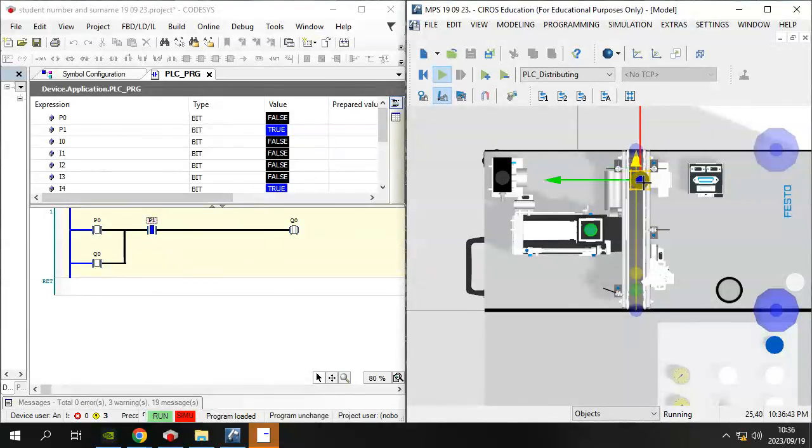Then let's go on top of them. So you see your, I think it's I2, or what is it? I2 turns on and off. So when it's not having a workpiece next to it, it's on. When you bring a workpiece next to it, it turns off. Then this other one turns on. Then that other one there at the bottom turns on. So you have sensors that come with different natural states, normally open and normally closed.